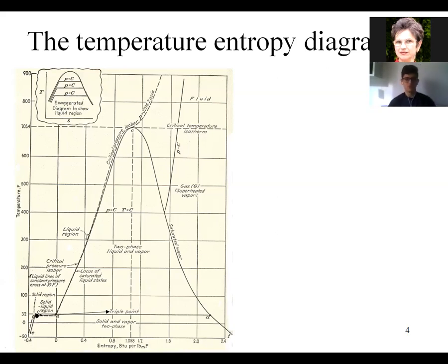all these points are representing water and vapor at equilibrium, at the same temperature that is named saturated temperature, and that is in direct connection to the pressure at which we are doing the process. The higher the pressure, the higher the temperature is. If we have here a point, let's take this point, we can say that from the tables that I mentioned, we will take values for the liquid here and for the vapors here. And in order to characterize this mixture, we will use these formulas with X. Is it clear?